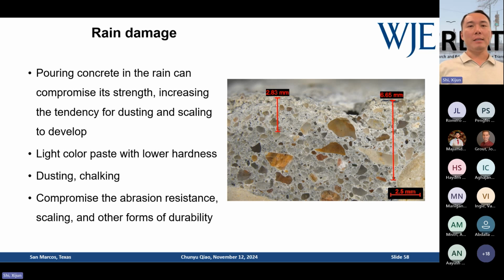So the rain damage, like I said, alters the surface water ratio, right? When I mentioned water ratio, the first thing you want to examine is the color variation. If you have a higher water ratio paste, your color is brighter, right? If you look at there, I don't know if you can see clearly because of light, but you see those red bars, compared to the paste in the middle, it's brighter at the top compared to the middle of the unaltered concrete.